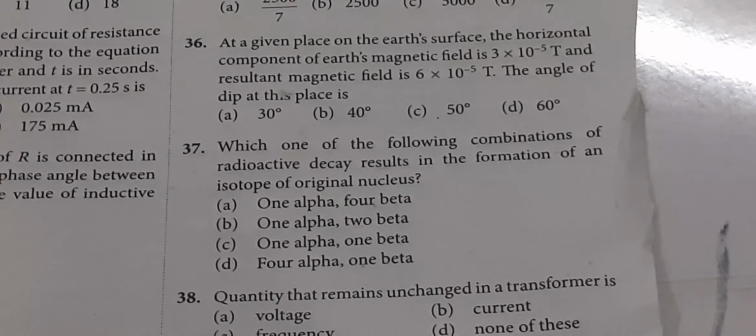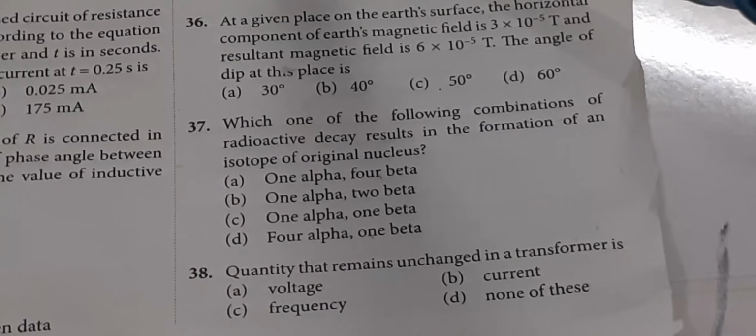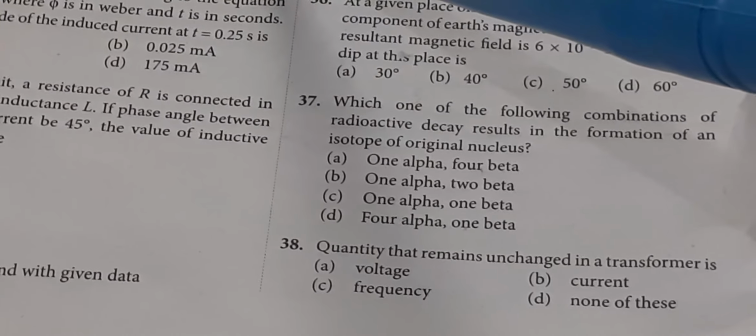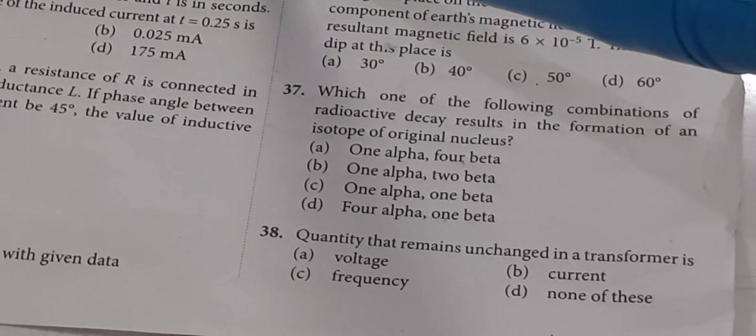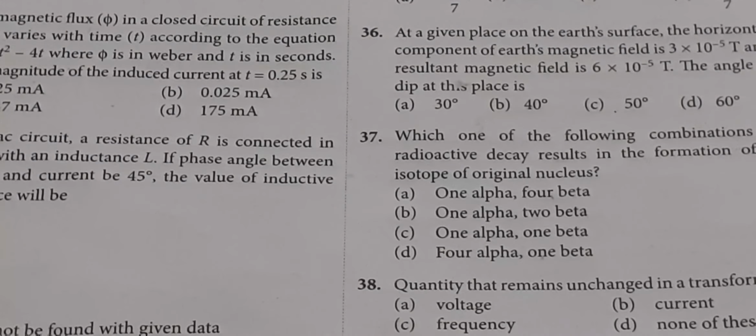Now the next job is, the quantity that remains unchanged in a transformer. Voltage can step up or step down, current also responds accordingly. Frequency is not going to change. Frequency is fundamental, it depends on the source only, not on the transformer.